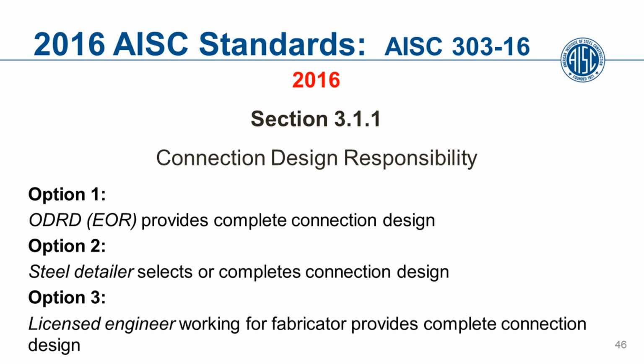Well, I think what you have to remember, a detailer selects or completes connection design from tables that are in the AISC manual. So when you look at tables in the AISC manual, it's pretty much selecting them from the loads that are given on the drawings. When you're reading about option 2 in the Code of Standard Practice, it's very essential that you read the commentary that accompanies it. So it does not involve any engineering. Developing of stiffening required for local loading is engineering. Sizing connections by selecting from a table with loads on a drawing can be done by a detailer.